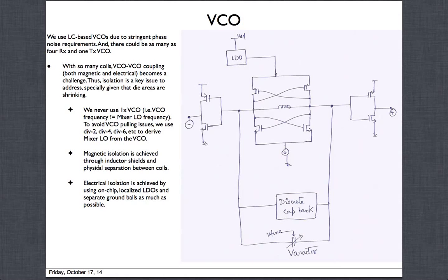The chip is not really big. These transceiver chips are really small. They used to be like 50 square millimeters or something, then they came down to 30, then 20, and now they're almost at 10 square millimeters. So take a chip which is about 10 square millimeters, roughly 3 millimeters by 3 millimeters. How much distance do you have to separate these guys? And these are not the only things on the chip, as I will show later on. It really does become a challenge.